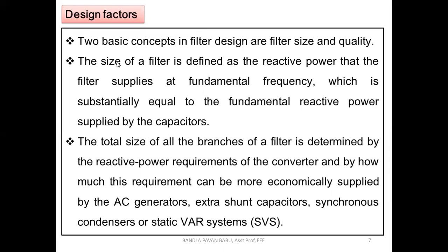Next, the size of a filter is defined as the reactive power that the filter supplies at fundamental frequency, which is substantially equal to the fundamental reactive power supplied by the capacitors. We know it's not about the DC side; we are discussing the AC side. So these filters which we are preferring for harmonic reduction can also be used for reactive power compensation, to a certain extent, because we are using different combinations of RLC components, which are nothing but energy storing elements. Either an inductor or a capacitor, definitely one of the components will be chosen there.